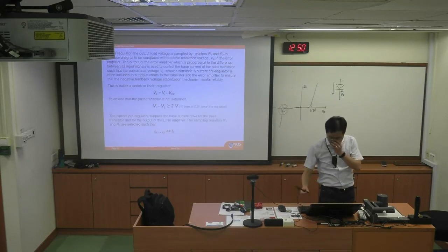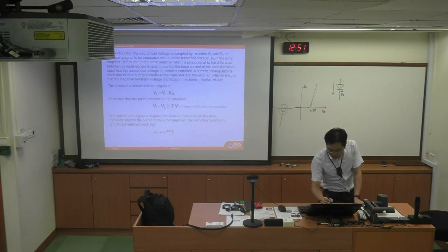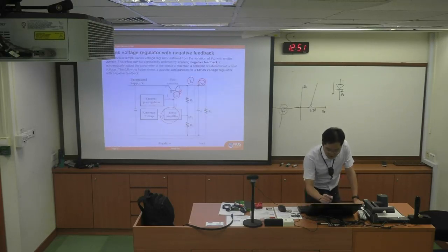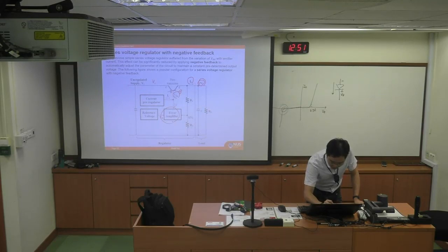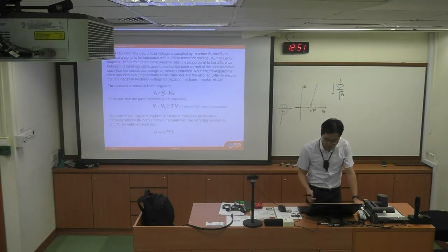In this case, first of all, the load voltage is the input voltage VI minus the voltage across the collector to emitter, VCE. That will be the output voltage.